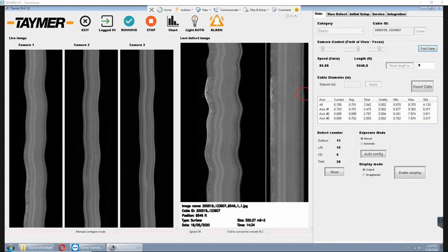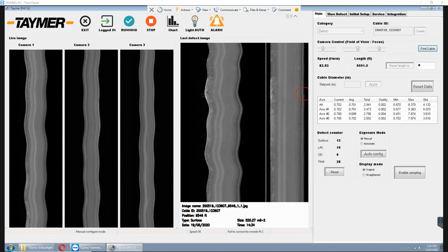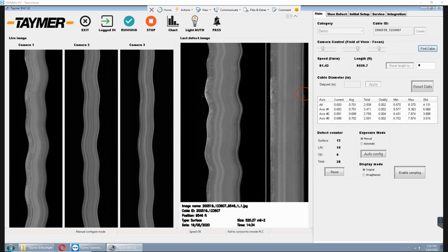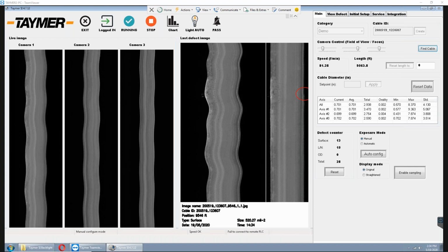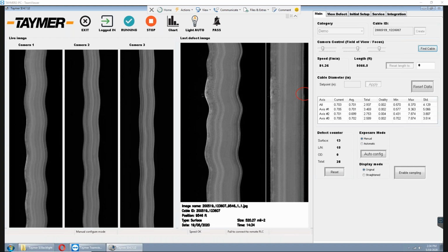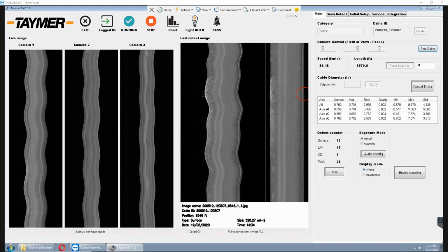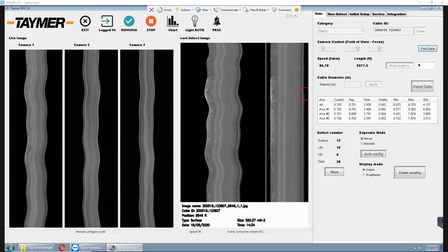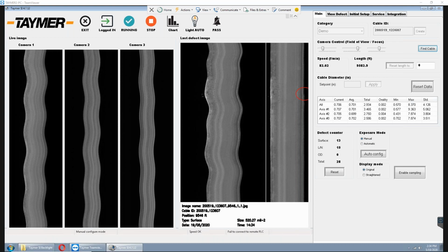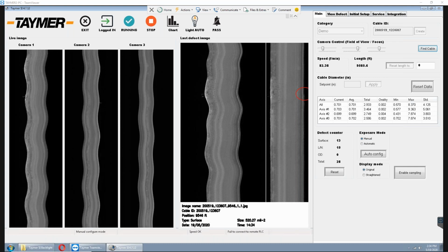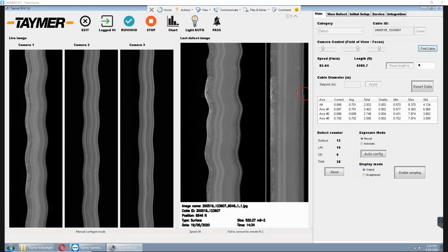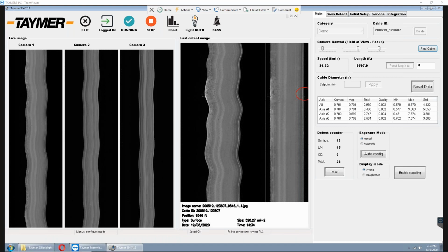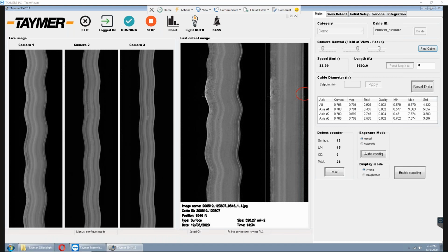Identifying those high legs is a manual process for us right now. Yeah, and so I guess the way we'd probably go about doing that, and Alex, feel free to step in here, is we'd probably look at the diameter of that cable as it's being inspected, and if that edge comes out as a lump from the center, you could detect it in that manner. Yeah, or likewise, if there's a gap caused by that, if I'm picturing the defect correctly,